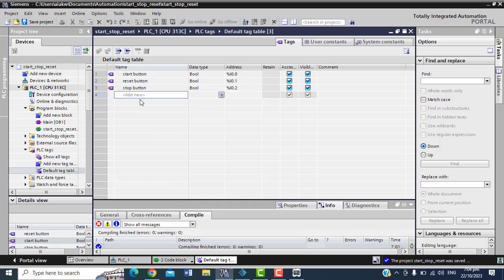Okay, so you see here now, they do say input and output. You go name both input, you go name both output, you go name both memory bit, everything. You go name them inside here. So this one they select this PLC tag table. You don't name input one side and output one side. You go name everything, both input and output. In fact, if you name one input, one output, one input, one output, they know if it is wrong or there is a problem.